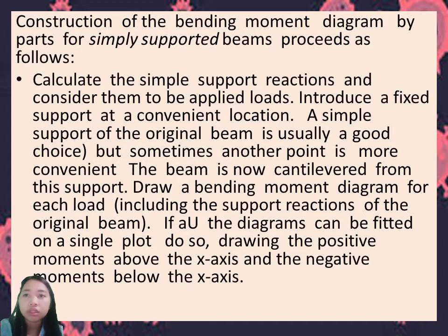So in the shear force diagram, the point of inflection is where the sign of the shear force changes. Basically, it means the beam doesn't carry any shear stress at that point. The point of contraflexure is the point where the sign of the bending moment changes.